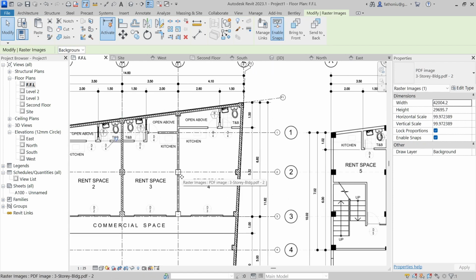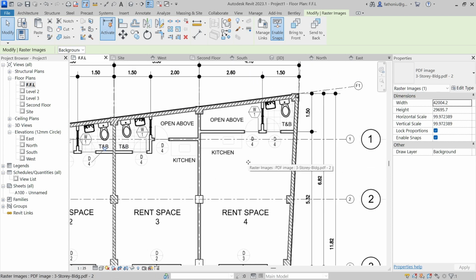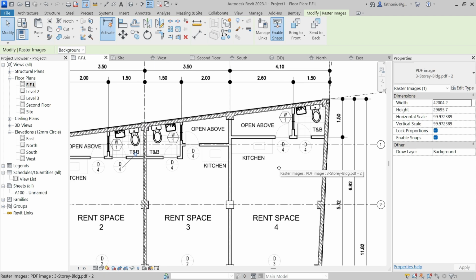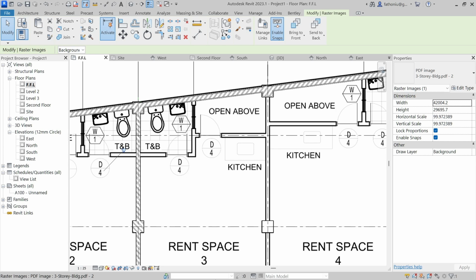The structural model is not necessarily very accurate, because this is for visualization purposes. But for the structural model, you have to be very particular on the offset, on the location, the intersection of the joint, beam to column, beam to slab floor, so the analysis will be correct.